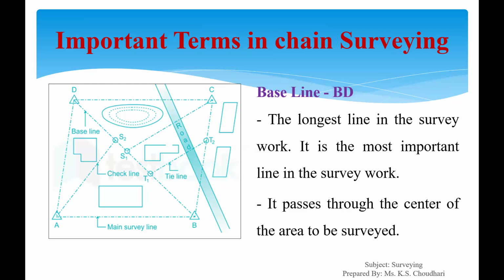Baseline BD. Observe the diagram. The longest line in the survey is the baseline. It is the most important line in the survey and it passes through the center of the area to be surveyed.